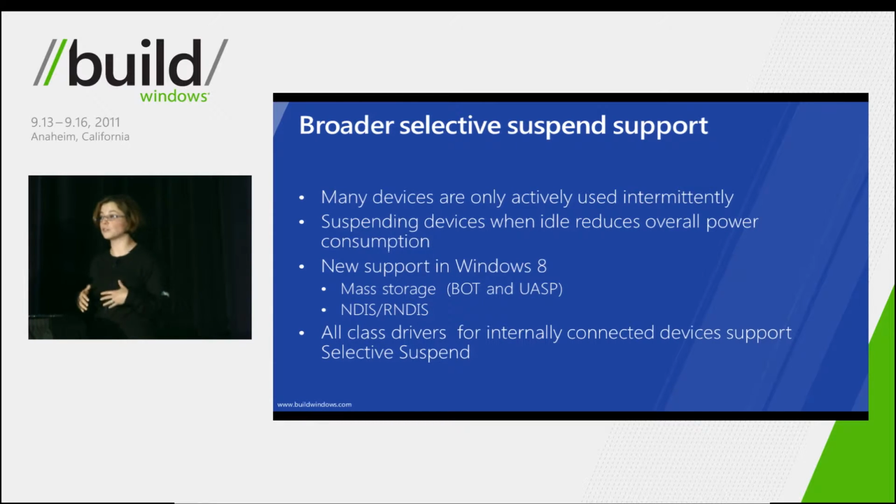So it allows for the system to go to sleep. This is in particular important for devices that are connected to the controller at all times, like embedded devices that are within the plastic. And so for all the internally attached devices, we recommend that you implement selective suspend very aggressively.